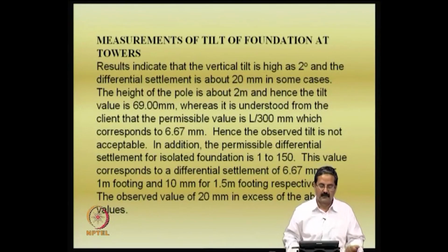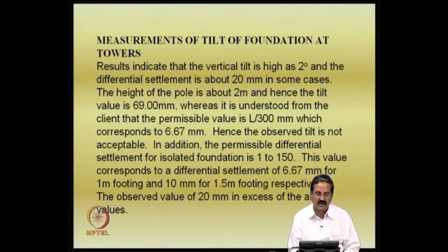So what I did was that I did a total survey. I first wanted to know what is the vertical tilt. The vertical tilt is how much of tilt is there in the pole, and then the horizontal tilt of the foundations as well as the vertical tilt of the vertical members. So when we did this with the total station, I was able to see that